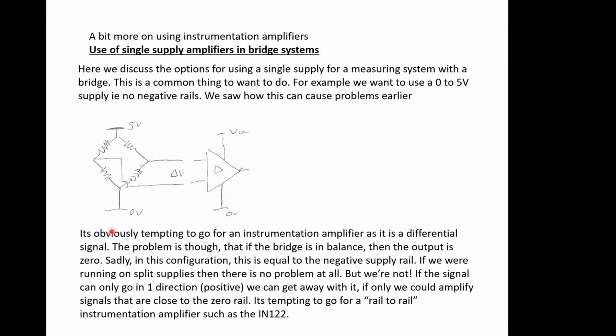So it's probably worth looking at these differential amplifiers in a little bit more detail, given that we've seen there might be issues with common mode and getting the system right. So the use of single supply amplifiers in bridge systems. People want to use single supply amplifiers because we normally operate on a single supply. You've normally got a battery or a couple of batteries, and it's usually referenced to 0 and then the other end at 3 volts or 4.2 volts or whatever you want. So op amps these days want to operate in single supply systems, so it's important to understand about those.